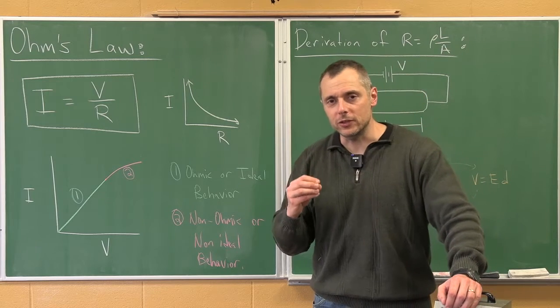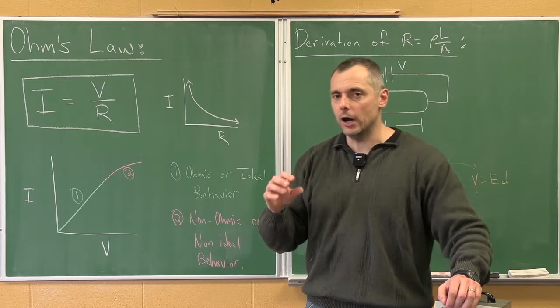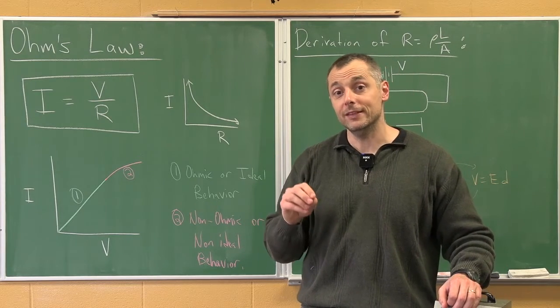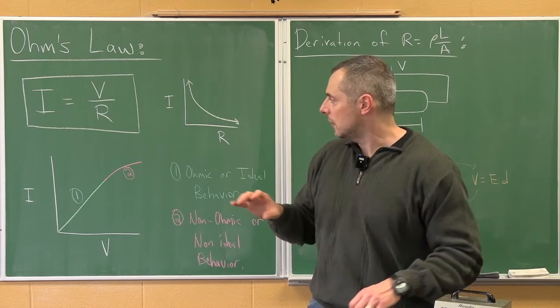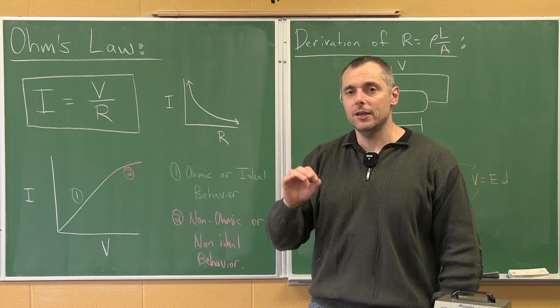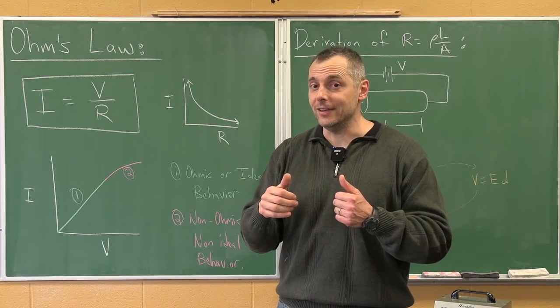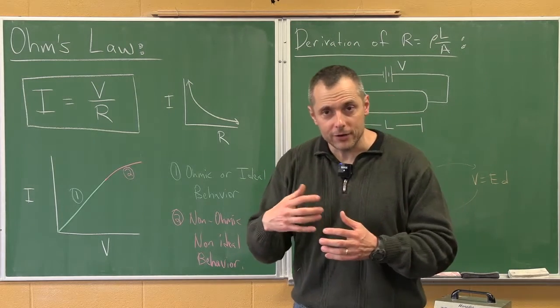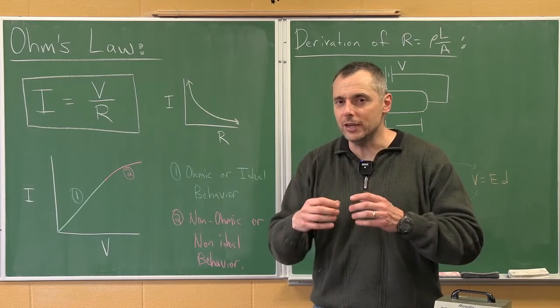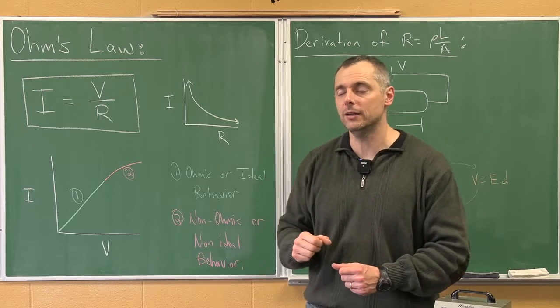And when resistors heat up, the resistivity, those numbers, those constants I looked up in the textbook, they change. Something that's not in the formula we learned is the temperature dependence. The hotter the resistor, the more resistance it has. And so for a lot of situations, the resistor doesn't heat up because it's able to dissipate the heat that the electricity creates in it.